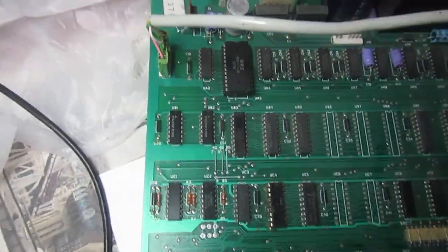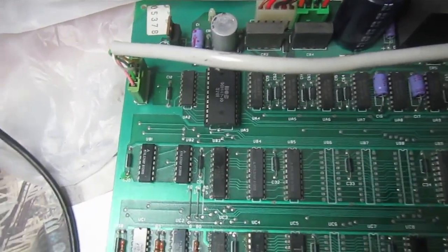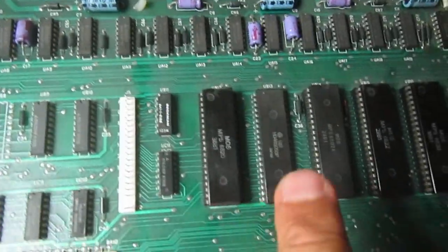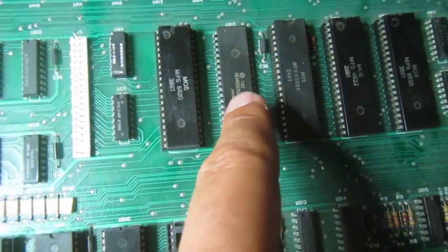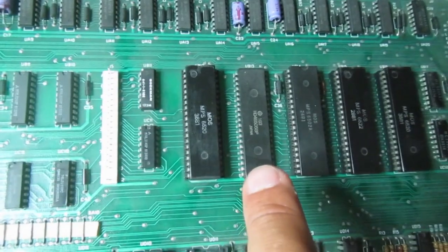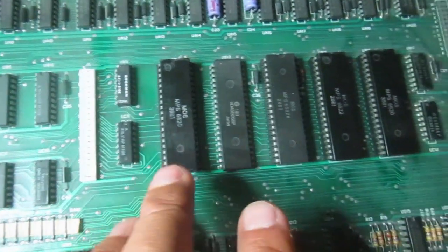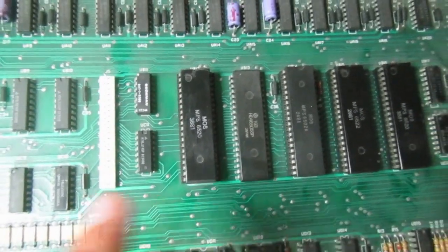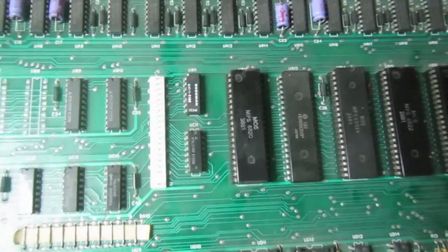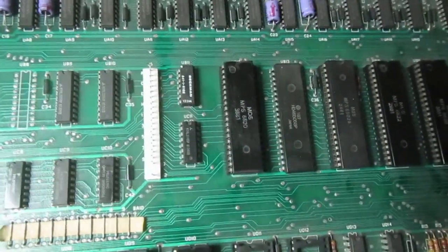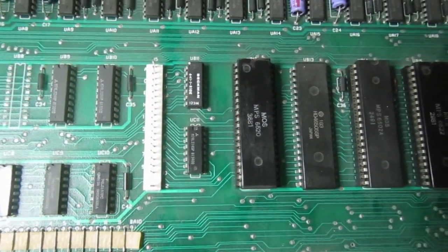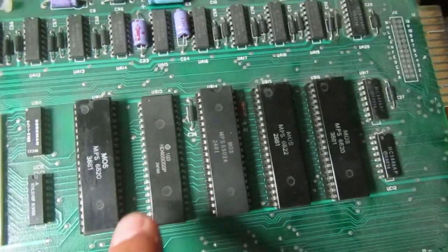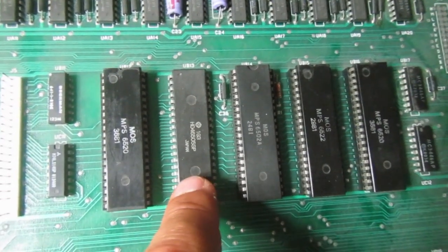And so let's begin. First of all, one of the problems with these universal boards and generally the Commodore PETs with CRT controller, well, not a problem actually, but for me it was, because I only have the 9 inches monitors for the old 2001N that have very different sync frequencies from the 12 inches CRT that use the CRT controller integrated circuits.